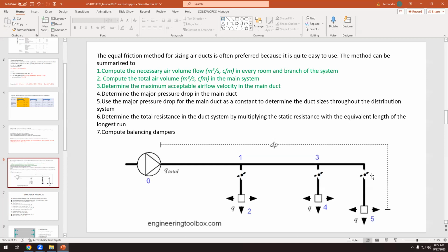So this is the source of hot water or air, whatever. So if all these pipes or ducts are wide open, what does the water do? It goes to the easiest path, and what is the easiest path? So if I'm water, why do I have to go up until the end of this if I can go here? So this is what happens. So we should have different valves, and this is what we have in water circuits and in air circuits. So we have to fix it.